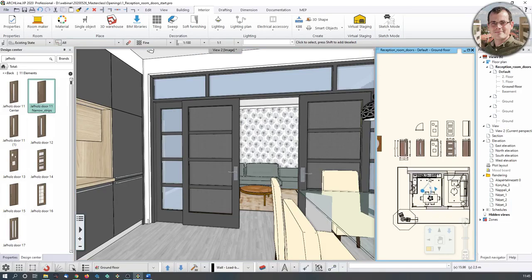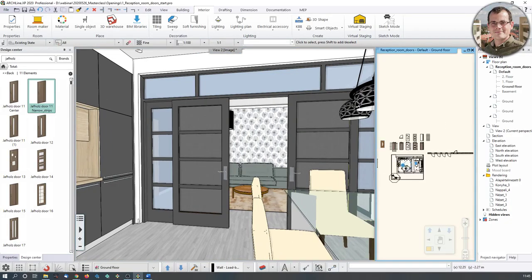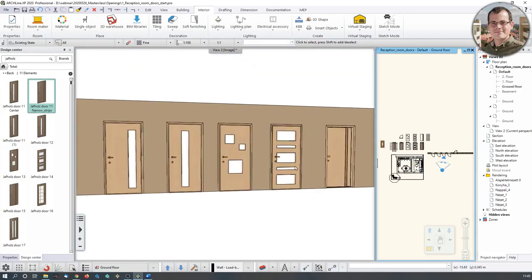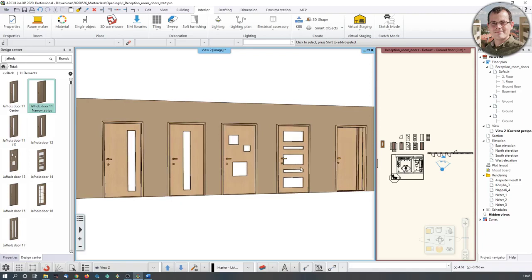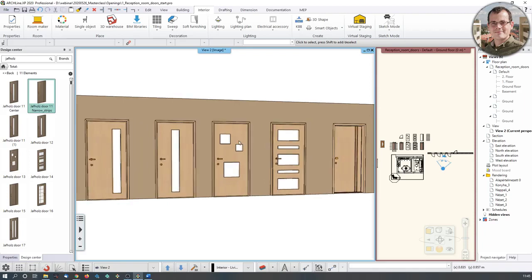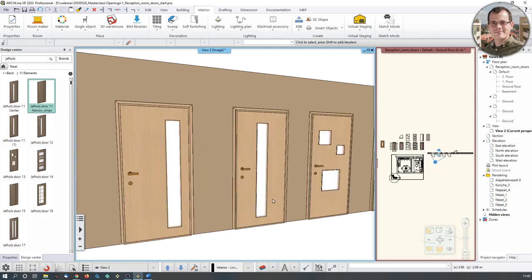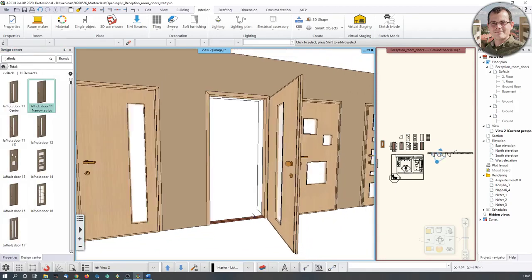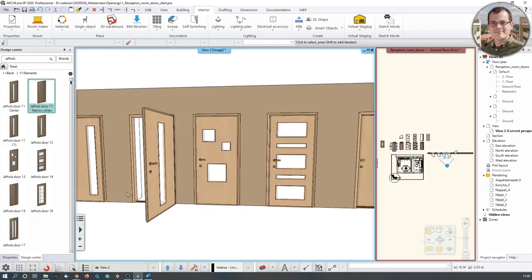And last thing I showed you is the door wizard, where we created these wonderful inset doors. And again, you don't have to do this work because you can work with elements that others have created, but if you have the time, invest it into using the door wizard, because that way you are going to create elements which are looking exactly the way you need them to be, and most importantly, you can open them up as well. So you can say that this is actually open. So wonderful. It's all parametric, it's all there. So there you have it.